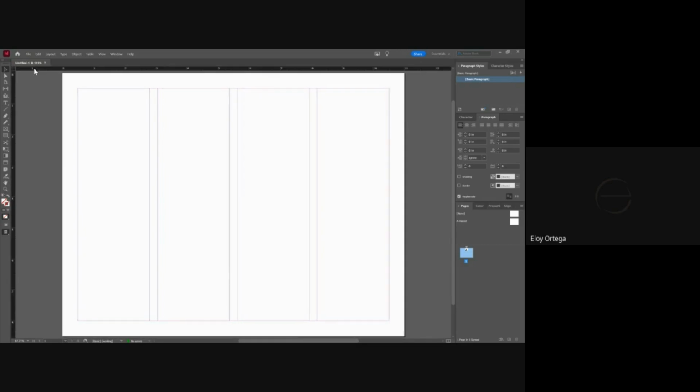And just for any guides that you need to create, once you have the ruler up, you could pull down from either axis and create a guide. So you could do something like this if you need to, and this specifies what axis point that guide will be in. And you can always select a guide and delete it.